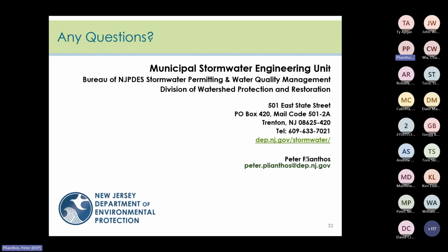Please see Example 7 in the chapter for guidance when replacing soil below an infiltration BMP. Also, Chapter 5 includes examples with groundwater mounding analyses and including exfiltration in the routings, which is allowed in certain circumstances for the green infrastructure BMPs.